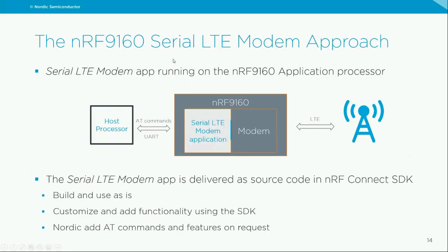So how has Nordic done this? We have basically developed what we refer to as a serial LTE modem application that runs inside the application processor on the 9160. And this serial modem application will be the interface to the outside world with AT commands, and will internally translate those commands either to use some stacks already running on the application processor, or AT command or BSD socket interface to the modem.